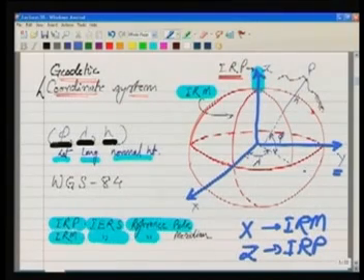Now, in this, any point P is on the surface of the Earth. From this point P, we can drop a perpendicular or normal onto the surface of the ellipsoid. So, this we say normal. Now, corresponding to this point, we will have a meridian. This is the meridian corresponding to that foot of the normal, and this particular meridian will make some angle with the reference meridian. This angle we say lambda, which I have shown over here. So, this is the longitude.